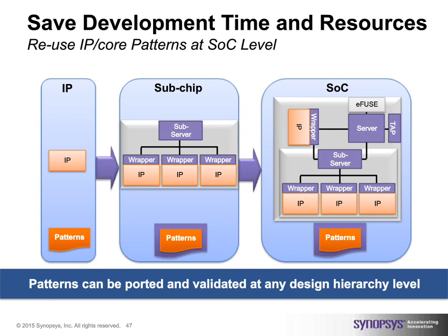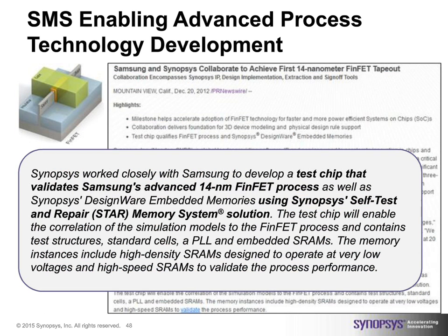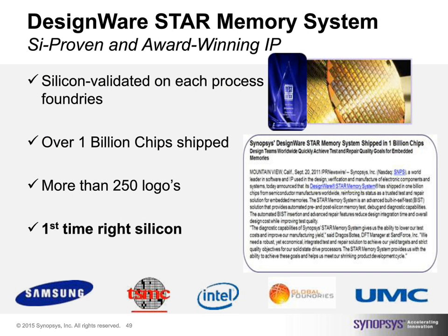Where do we stand today? Today we stand at the 14, 16 nanometer FinFET solution, looking at the 10 nanometer cells and their defectivities, analyzing them. With that, we have put in effort, and are continuing that effort, to understand the silicon and to validate it. We have had a large number of chips that have used our solution in the past and continue to use it today with very good success so far. So we see first-time-right silicon coming out, and that encourages us to continue our work.